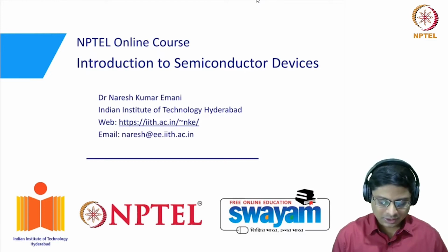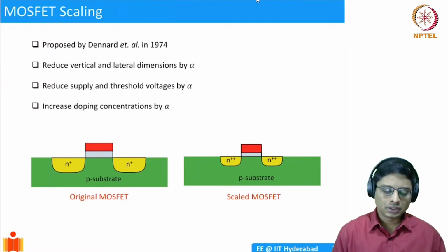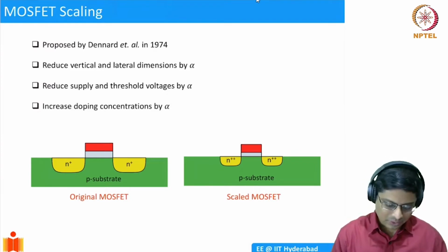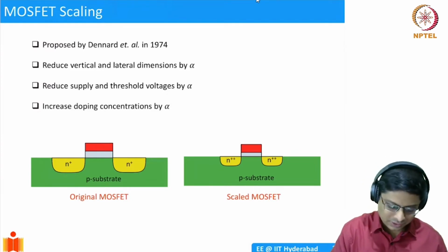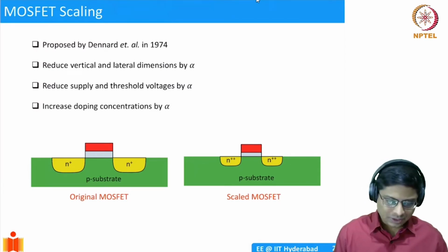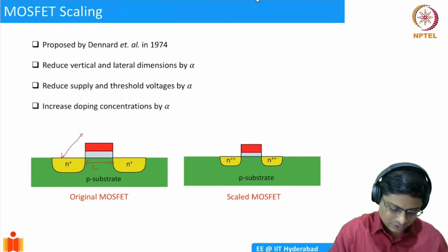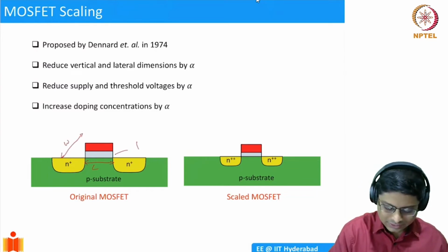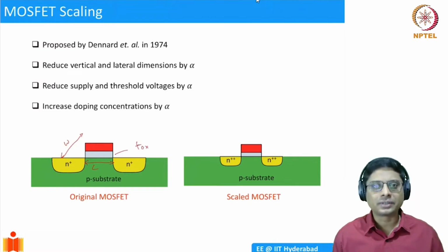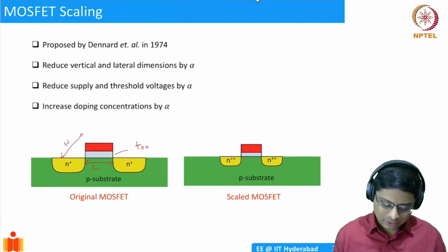To start with, I would like to introduce the concept of scaling. Scaling was first proposed by Dennard and co-workers in the year 1974. So the essential idea is this. We have the MOSFET, we have seen this. We have the source, the drain, and the oxide thickness, and the gate, and all that. So we have the various parameters of this MOSFET, such as the length here, and then there is this width which is going into the plane of the sheet here, and then there is oxide thickness, and then the doping concentrations. Right? These are the most important parameters to calculate the threshold voltage and so on.